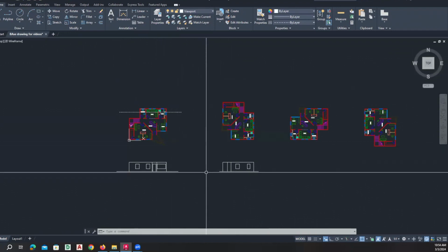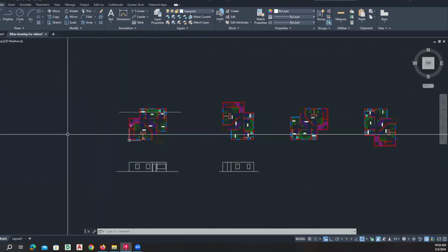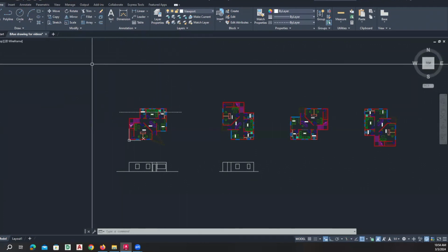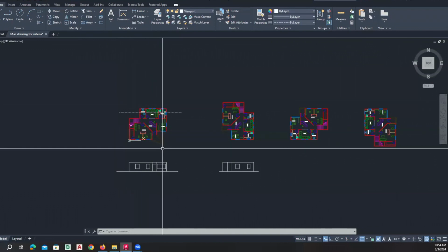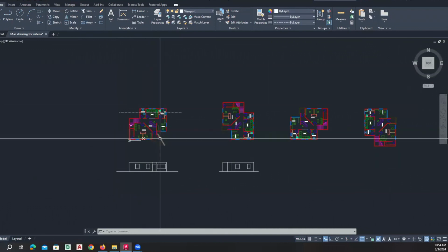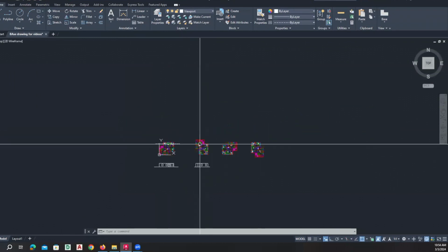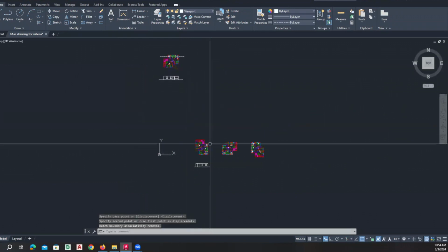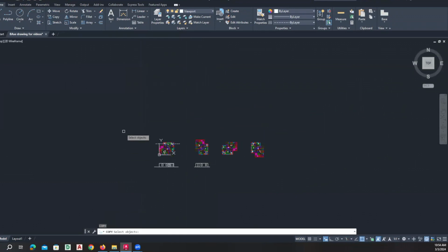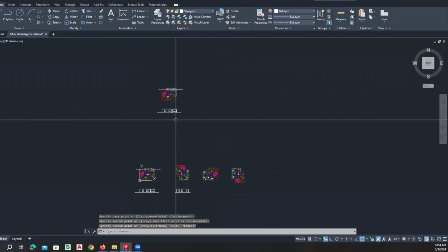And what you'll see is that those elevations and sections will be rotated around this plan so that they will all be parallel to the faces they're referencing. And then when I make a change, I'm only changing it once, and I could just reproject the components that I need to reproject. Okay, so to begin with, I'm going to leave this here, just floating here for now, and I'm going to copy this elevation up here. Oop, not move, I'm going to copy. Okay, so that's going to exist up here.